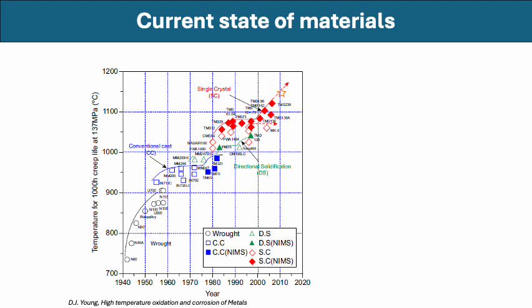We don't know whether it is going to continue in this direction. We are going to increase the operating temperature incrementally, or we are going to suddenly go to a new technology where a sudden jump in operating temperature can be achieved. There is numerous research into some refractory high entropy alloys and some titanium and chromium based superalloys.